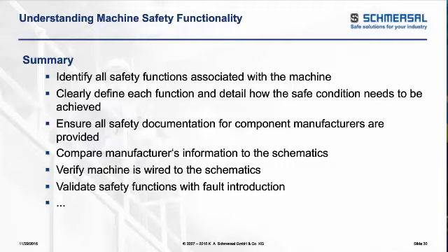Which leads us into, you really have to make sure you have all the proper safety documentation from all the component manufacturers. Meaning any of your output devices, you have to have their installation instructions, especially nowadays where they do have safety functionality built into it. It's not just doing what you did in the past, it's doing it per their recommendations.